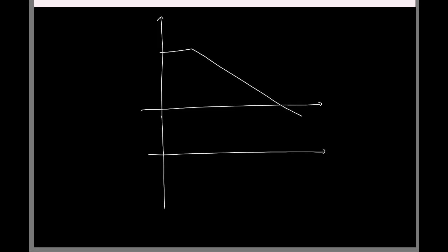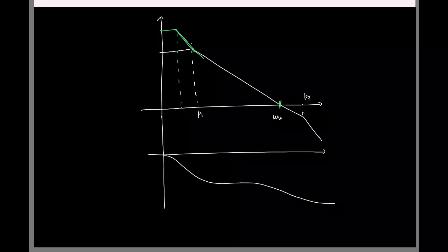Let's say initially you have something like this. This is omega u. I have P2, and P3 comes later; I'll ignore that. The phase is doing this. Now this is my earlier P1. If I reduce G1 and G2, what will change? P1 is changing, omega u is still the same. At omega u, the slope is rising by the same 20 dB per decade, so it will rise like this. Let's say here is your first pole. Assume it's a straight line. This is your new first pole, with the higher DC gain. And the phase will probably do this. It will attain 90 degrees quickly, but again it will follow this.